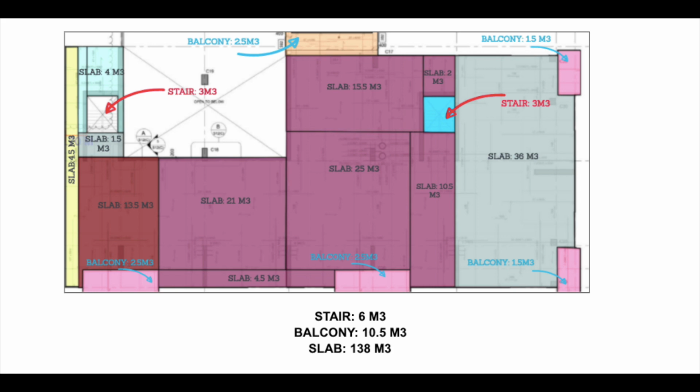Once the bulkheads have been established, I will then go and get a hard number for the width and the length for the overall slab area, and then adjust my areas highlighted in PLANSWIFT to suit, and that way my estimation number is more accurate and can be used to order the concrete.